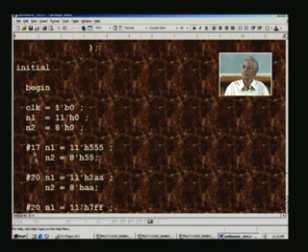So, in all the designs you would have noticed this: the very first inputs, the clock has to be initialized, because we are going to run the clock, and that also has to be initialized to 0. Later on the clock will keep on toggling as positive going pulses, and n1 and n2 are the two numbers we have already seen, 11 and 8 bits respectively. We are forcing them to 0 to start with, and later on every 20 nanoseconds, with the exception of this, we change the data, in this case 555 then 5, this corresponds to 0 1 0 1 and so on.